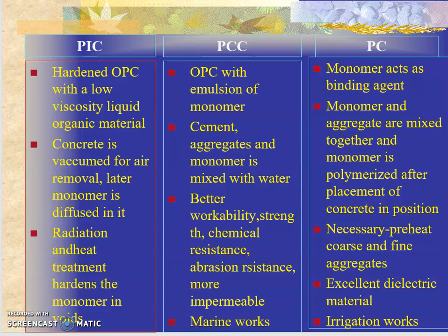First and foremost, the application of these concretes is in a very wide range of construction activities. It's used as repair mortars. It's used in bridges or roads. It's used a lot in irrigation works. And basically, why do we go for these polymer concretes? Obviously, understand one thing, that the cost of this particular concrete will be way higher as compared to the regular PCC or regular RCC. The reason being, this polymer that is added is itself not a so cheap material.